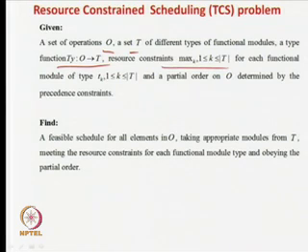So, what does the resource constraint say? It says that K is a type of operator, like an adder, a multiplier, or a subtractor, and it has a limit. It says that it is 1 to max of T. So, you can say I will use a maximum of 2 multipliers. So, K is the type. Like in this case, for each functional type Tk, you can have an inequality like this.